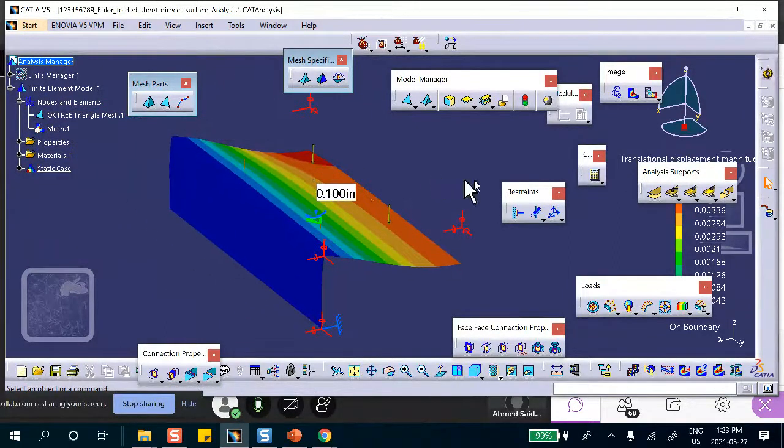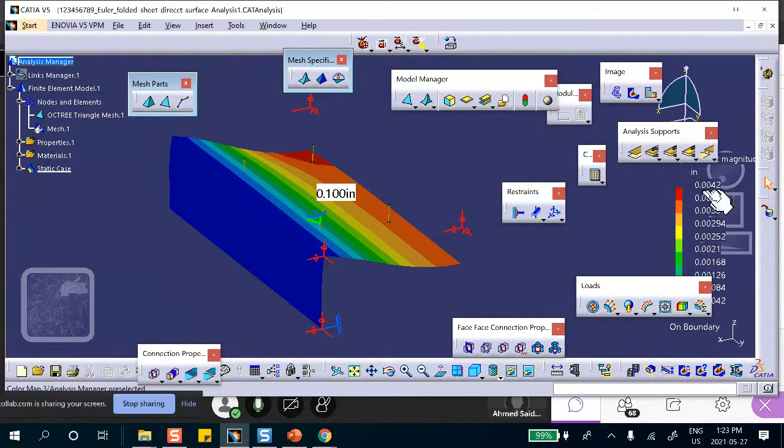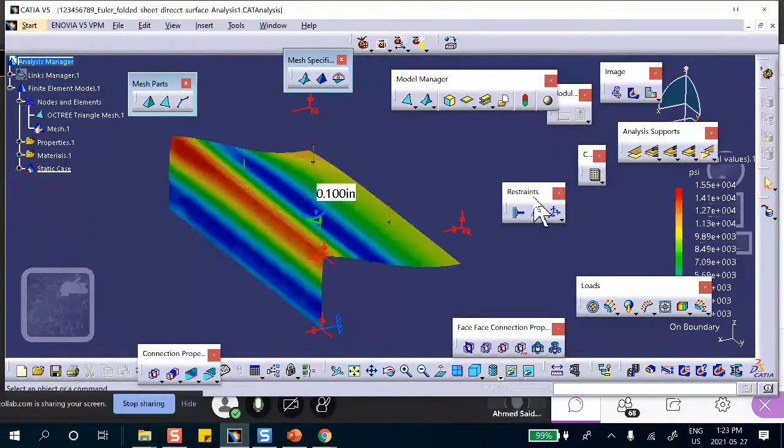Okay, all right, good. I don't know, what are these numbers? 0.0042. Okay, it gives you some idea, but is that all you care about? Well, many people are interested in yielding and things like that. So you come here, it says 15,000 psi around that edge. That doesn't surprise you because this is a folded sheet metal with a 90-degree sharp corner here. So you expect some nasty things happening there. 15,000 psi around that edge, okay?